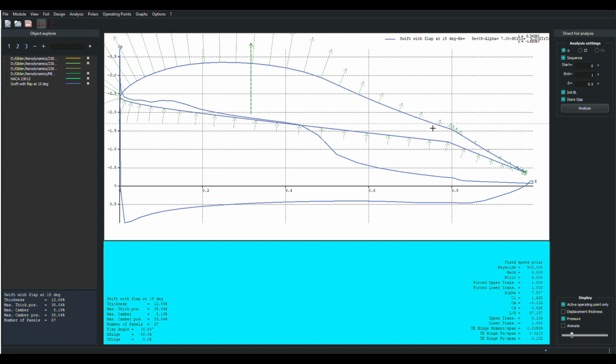There is a bit of a corner to turn because we have a significant kink in the continuity of the first derivative, because the slope is going one way here, and then all of a sudden the slope changes the other way here, and so there is a bit of a corner to get around. But the pressures are very well behaved all the way back until we get to the very trailing edge, and that's exactly what it flies like. And it works. That's why this works. It's not a flat plate stuck on a trailing edge, but close to it because of how the pressure distributions occur on the airfoil naturally.